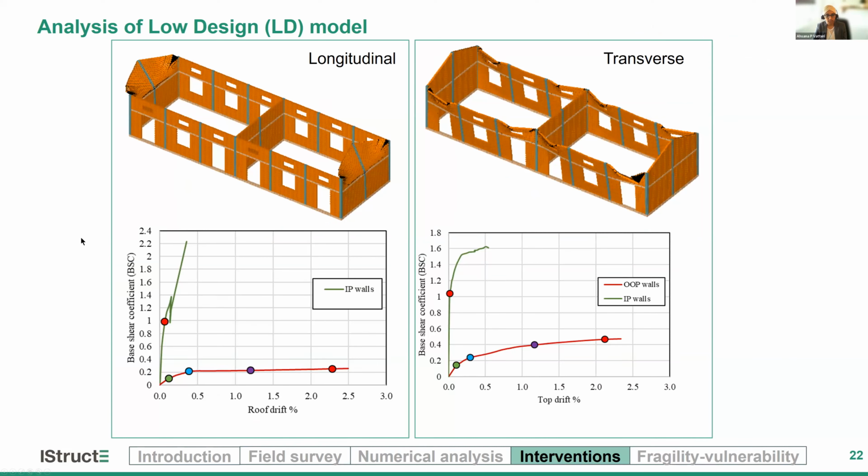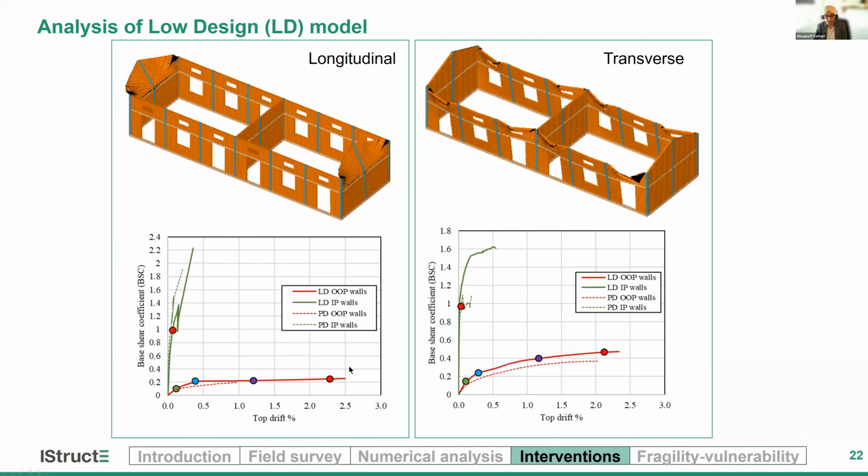So as compared to the previous case, you can see here that this case with better connections has more deformability, and in the transverse direction, it also has better strength capacity. However, we still have a lot of difference in the deformation of in-plane and out-of-plane walls.